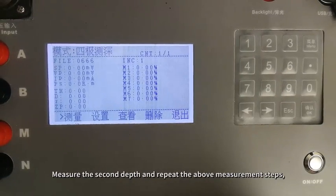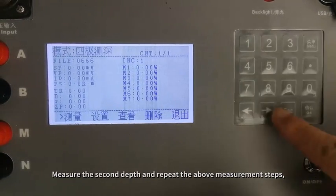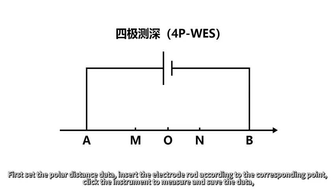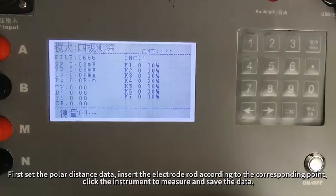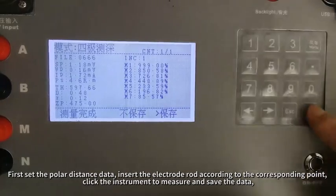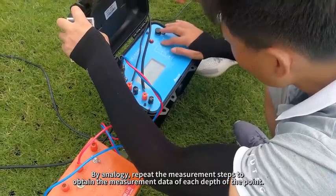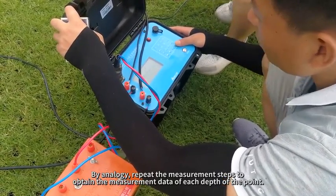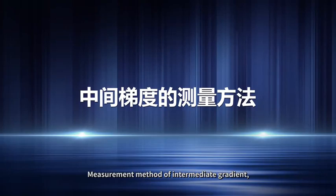Measure the second depth and repeat the above measurement steps. First, set the polar distance data. Insert the electrode rod according to the corresponding point. Click the instrument to measure and save the data. By analogy, repeat the measurement steps to obtain the measurement data of each depth of the point. Measurement method of intermediate gradient.